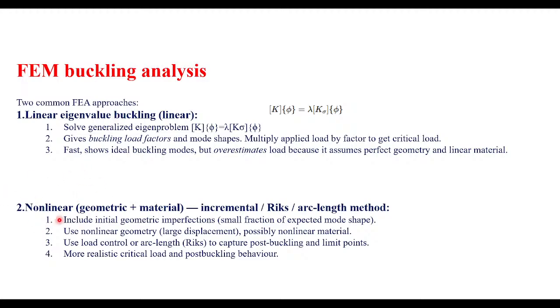Next, what exactly do we do in non-linear buckling? In non-linear buckling, we consider the geometry non-linearity into account. Let's say you already know about engineering stress versus true stress. If you go through that, you'll get to know what geometric nonlinearity is. And then the material nonlinearity also, the stress-strain curve will take it. With respect to the incremental and arc length methods, these are the methods we use to extract the nonlinear buckling.